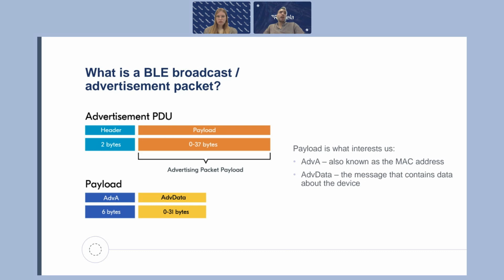This ADV data section is where the temperature values are contained, for example, as well as battery information, sensor status, and other telemetry values. Our tracker receives this information and starts processing it according to the configured rules or the protocol. Understanding this structure is extremely important when you are integrating custom BLE sensors.